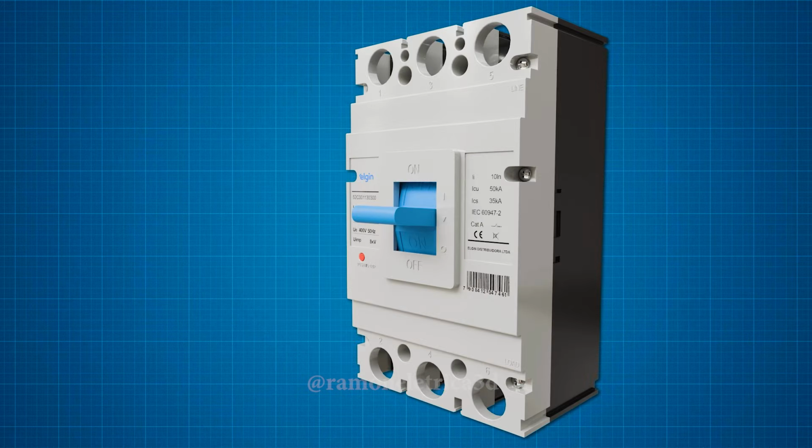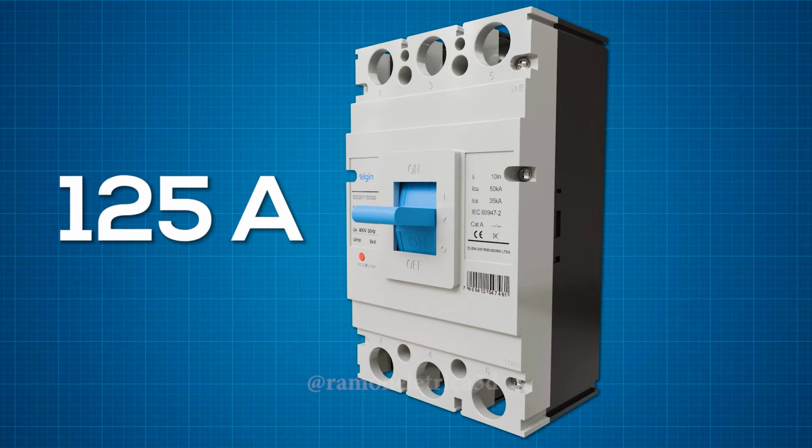For example, if you have a circuit where the rated current exceeds 125 amps, the MCB will not be sufficient. In this case, using an MCCB is mandatory, as it can handle much higher currents.